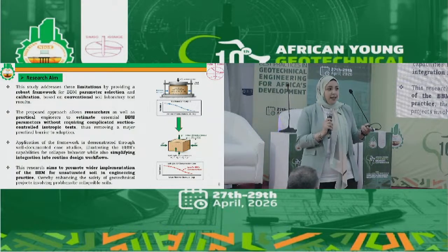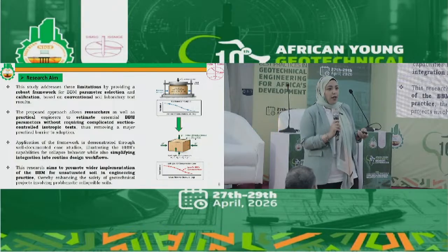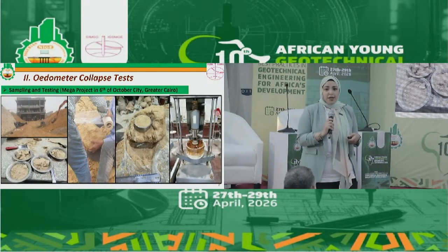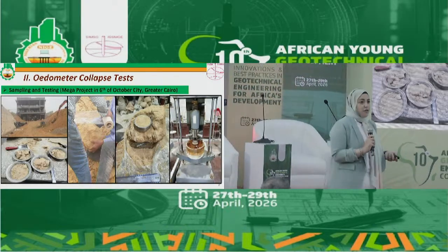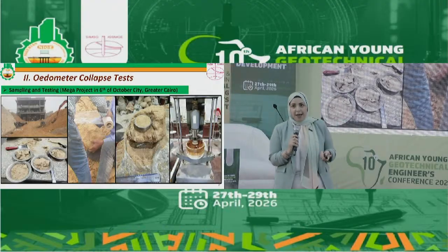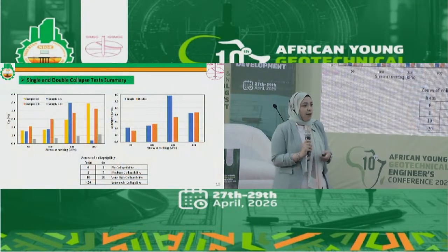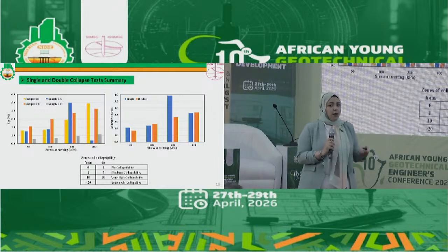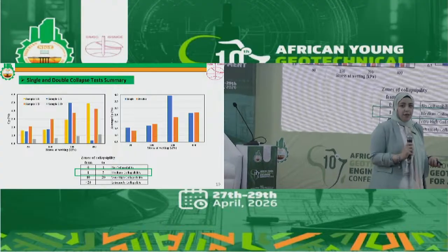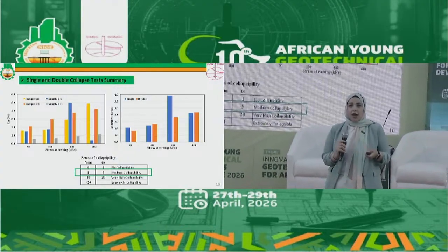So the whole idea is, since the BBM was formulated in a 3D isotropic state, we need to find an equivalent so we can get the parameters. In my research, I took samples of some soil in Egypt, and we did some tests on the samples. This was the collapsible soil we used. And we performed single and double odometer tests on many samples so we could determine the collapse potential. It turned out that this soil was in the medium collapsibility zone, so we had to study it and make sure that we knew the exact behavior and try to model it accurately.